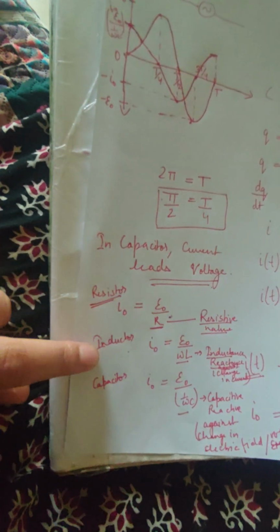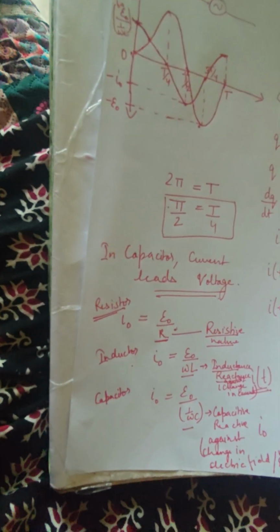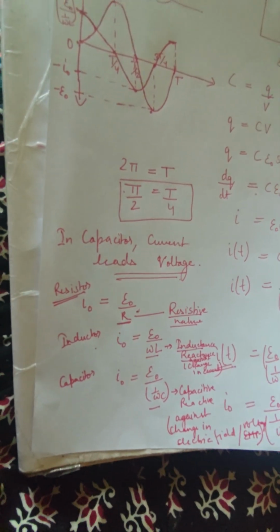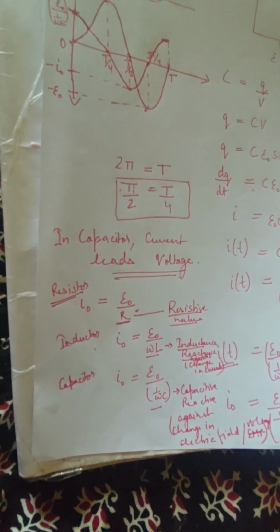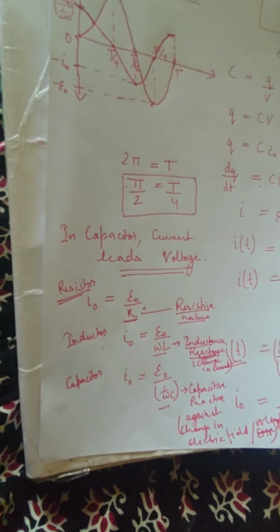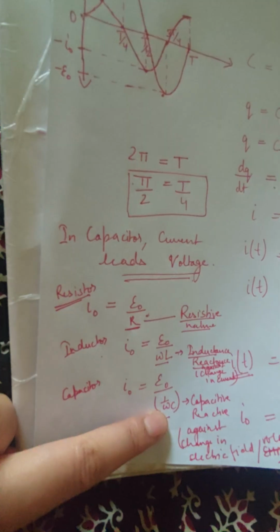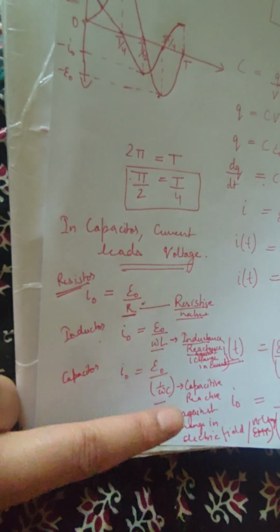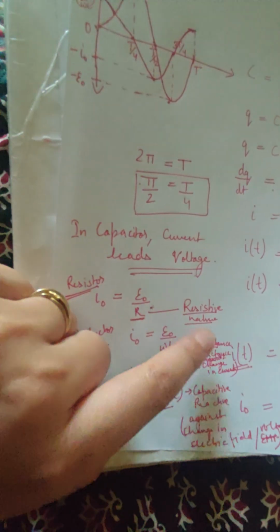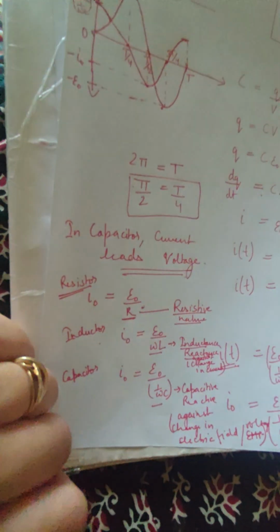But inductors behave differently because they have a factor of frequency involved. So they depend on frequency, and frequency decides how much current they allow to pass through. This variation decides whether the circuit allows AC to flow through it or not. Similarly, a capacitor also depends on the frequency of the external source that we have provided. So that's why, since they are frequency dependent, we have given them a different name, which is reactance, not resistance.